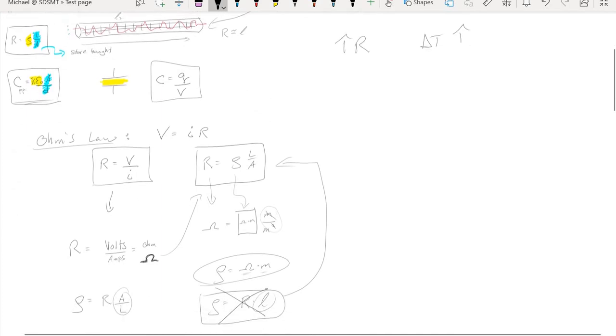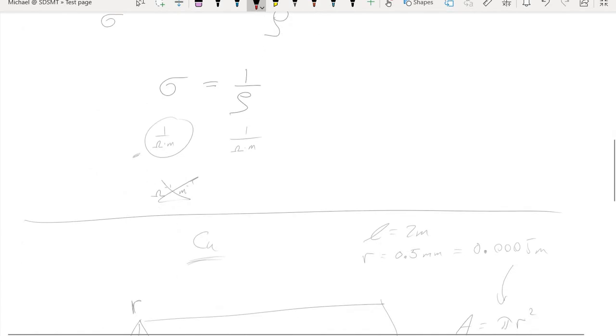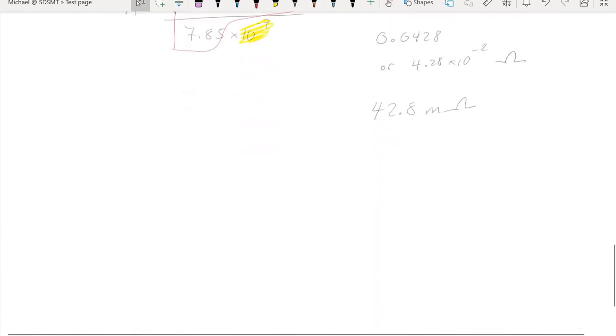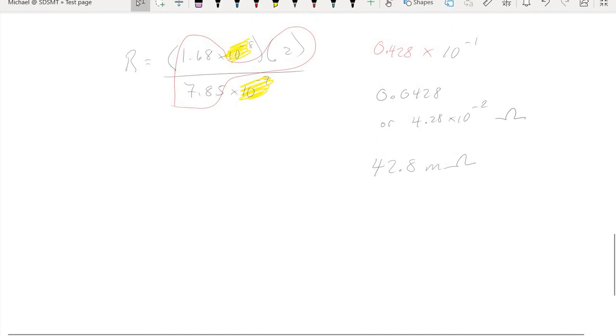And for materials that start generating heat, as we have heat that's being generated inside these materials, if that material can dissipate the heat at a rate that is at least equal to the rate at which the heat is being generated, then it can maintain a constant temperature. It can maintain a constant operating temperature, so to speak. But if the rate at which heat is being generated is much higher than the rate at which the heat can be dissipated, then you run the risk of your material melting. And in the case of electronics, this goes back to the idea of seeing the little blue smoke or smelling the little blue smoke, because at that point you've probably destroyed the object, you've burnt out the resistor.